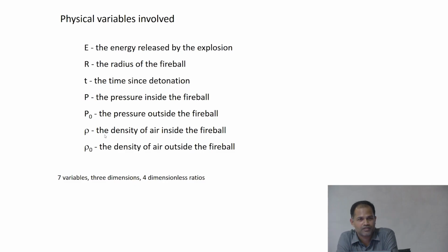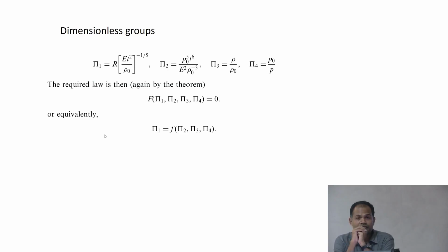So let's say if these are the variables involved, then what could be the relation that exists between these variables? Now you know how to do that because you know Buckingham Pi theorem, or you can use Ipsen method. Find out what are the non-dimensional numbers that are going to come up. So that's the way Taylor chose to represent, but you might probably get some combinations of these. You can actually verify that, as we said, it can be represented in many ways, depending upon what you choose as your repeating variables or what you select as your fundamental dimensions. You will get different combinations, but they would represent the same thing. So if you are getting, let's say, pi 1 and pi 2, if you combine pi 1 and pi 2 in some particular fashion, you are going to get the same non-dimensional number that he has written there.